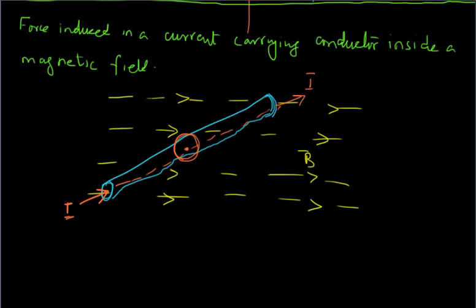The method is simply to use the right hand rule again. How to place your right hand this time is slightly tricky. For example, I'm placing my right hand. First of all, make sure that the fingers of your right hand are pointing in the direction of the magnetic field. It's very logical because the field has many lines, so you have many fingers and you can point those in that direction. Secondly, your thumb needs to be pointing towards the direction of the current.